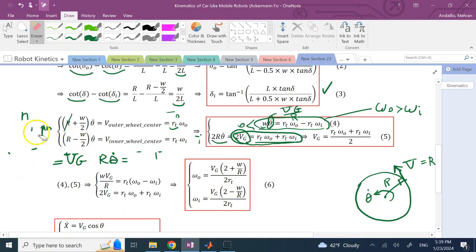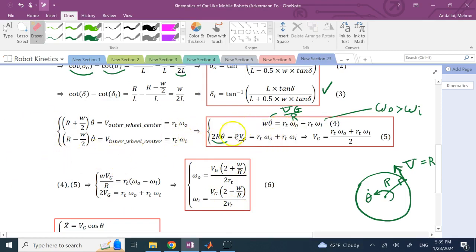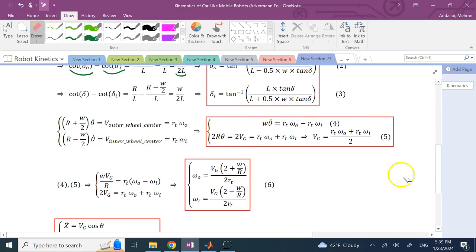at the inner and at the outer what? Wheels, and that is the job of the car differential, to make that difference basically happen in a passive manner. Okay. So differential does not control omega I and omega O directly. It's indirectly allowed by the combination of all of the gears in it. And maybe I make a separate video and explain that.